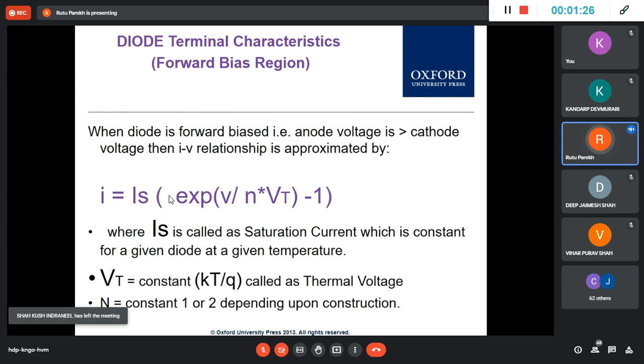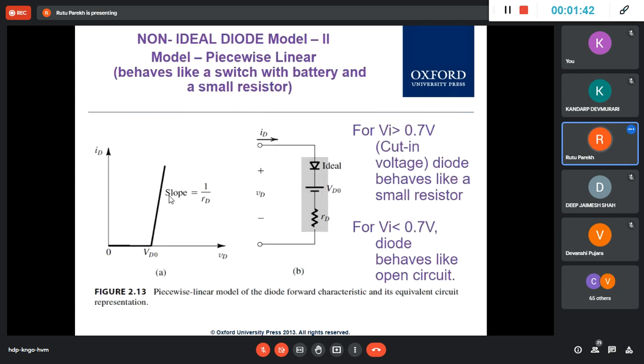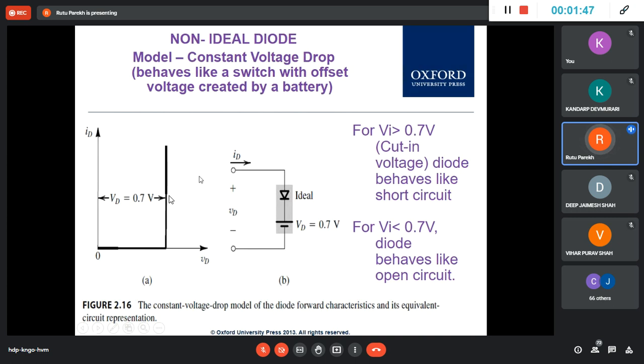on. So when voltage is the concern, and we are working at high voltages, to get a crude kind of analysis, we do use this ideal diode model, right? Then linear, we saw all this, right? So this was the ideal diode model we first used. Then this is the constant voltage drop model, where you will see a constant drop of 0.7, and we approximate that after 0.7 unlimited current will start flowing and the drop will remain 0.7.